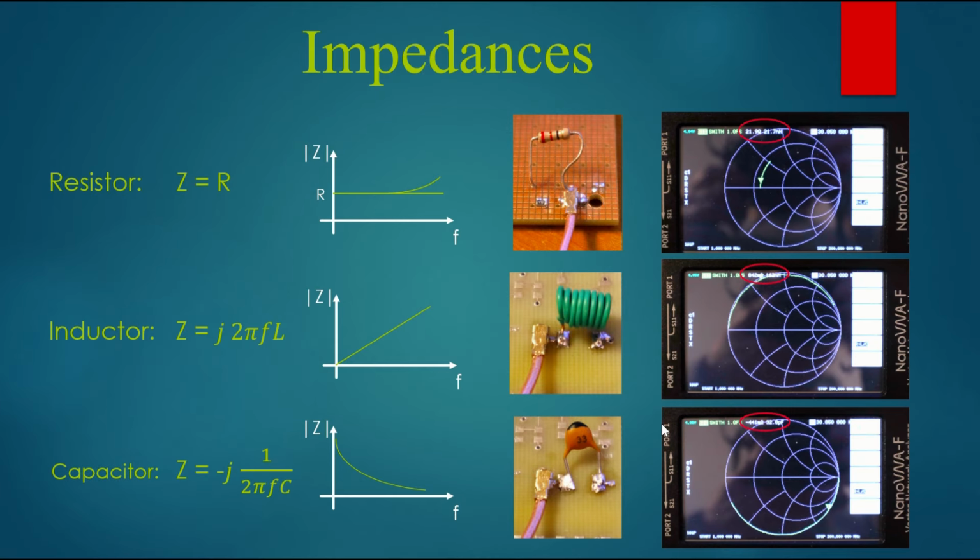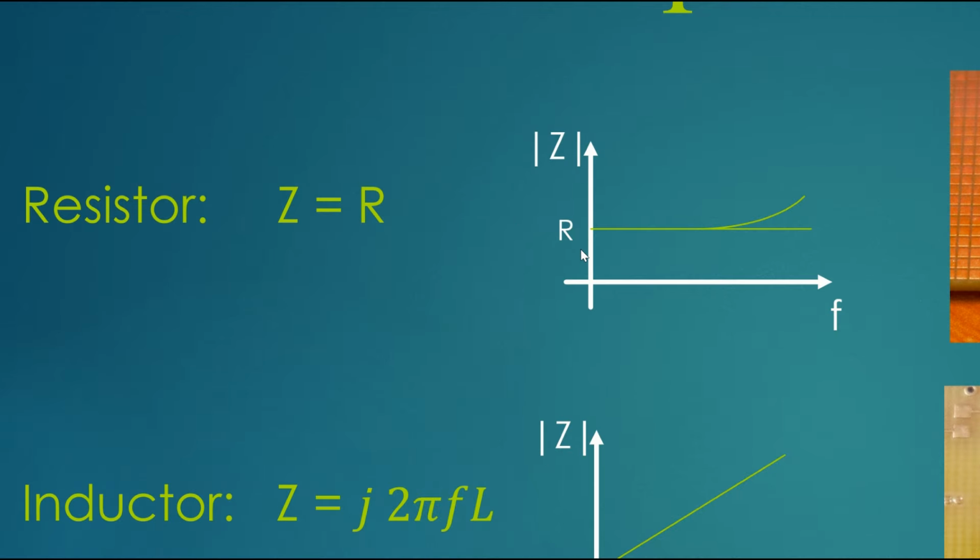Impedances. All right. So a resistor has an impedance which is ideally constant with frequency. Here there's a graph that shows the impedance Z. I'm just plotting magnitude, that's the vertical bars here, of an impedance. Here it's a resistor, so it's just a real number, and it's constant versus frequency, which is the horizontal axis. Except at very high frequencies.